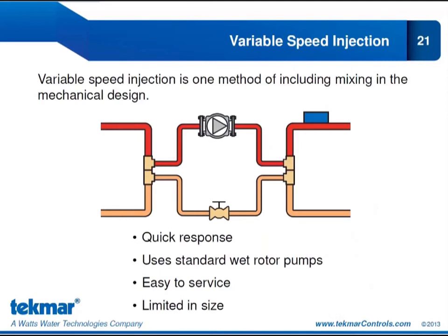Variable speed injection is one method of including mixing in the mechanical design. There are, of course, other options such as mixing valves. But the reason we're going to be focusing on variable speed injection is because that is what the 406 house control supports. The 406 will only support variable speed injection. It does not have the ability to operate a mixing valve.